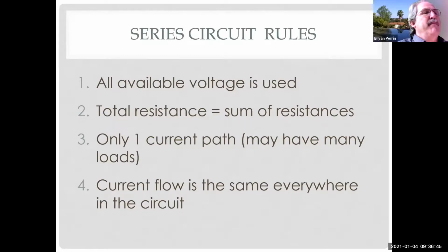So it doesn't matter whether my load has 2 ohms of resistance or 2,000 ohms of resistance. It's still going to use all of that 12 volts if it's the only load in the circuit. So the amount of voltage doesn't change based on the size of the load in the circuit. Current flow does, but the voltage doesn't, and it has to use all of it.